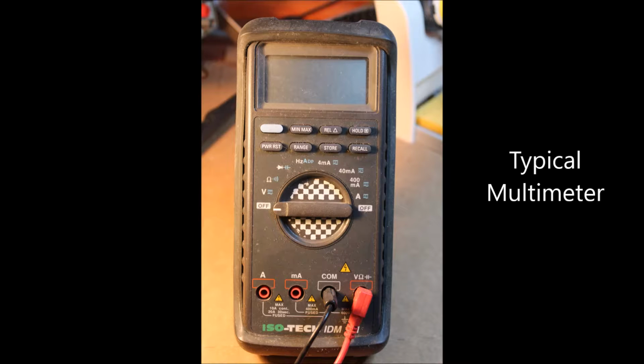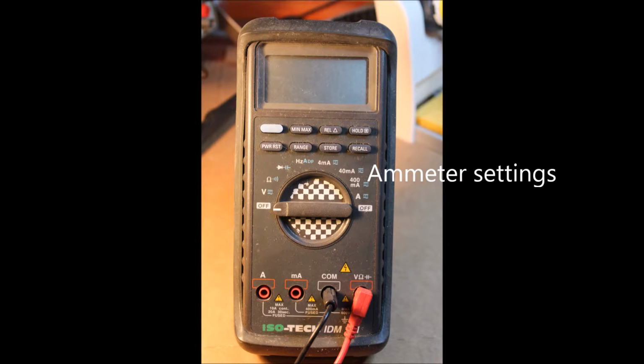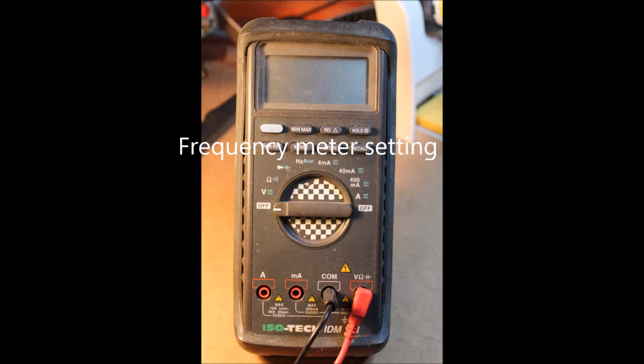The most basic item of equipment in any electronics lab, and the minimum needed if you're a hobbyist in electronics, is a multimeter. This instrument has three basic functions. It can act as a voltmeter or an ammeter, or to measure resistance, an ohmmeter. Many modern ones also have many extra useful functions built in. For example, frequency readings, device testers for testing devices like diodes and transistors, and even some simple oscilloscope type features.